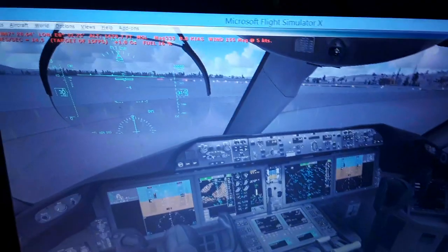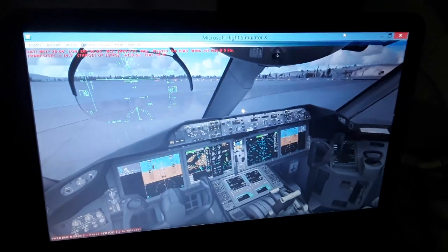So we can see also the aircraft when it's flying above the ground in the vertical display. We have also the terrain map with the airports. You can see the airport where we are located, and the runways and the taxiways we're going to use for takeoff and for landing are displayed. Also from the GPS receiver, you can see the runway length and its heading. We can see the VOR stations, ADFs and DMEs, the navigation aids of the aircraft. We can use also the waypoints, which are horizontal and vertical navigation fixes with altitude and airspeed constraints. We're going to use some waypoints using the flight management computer over here when we fly.